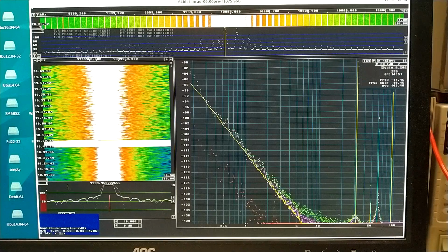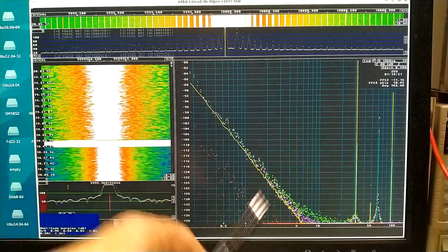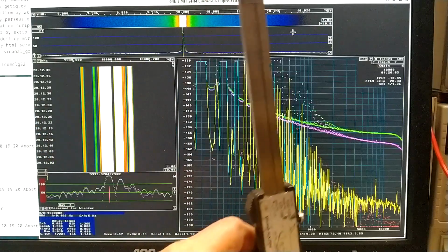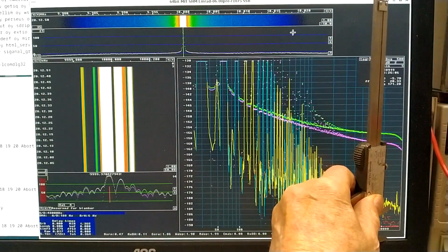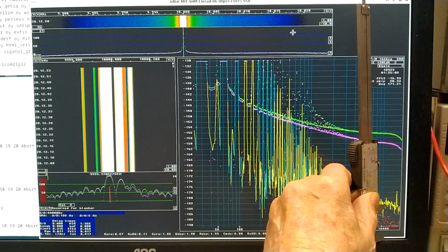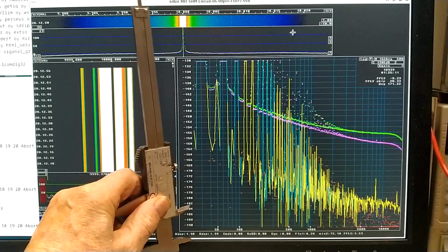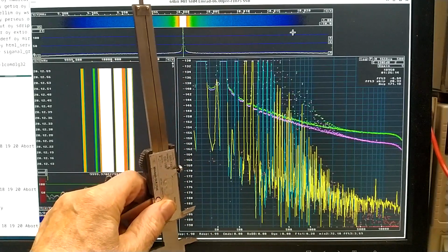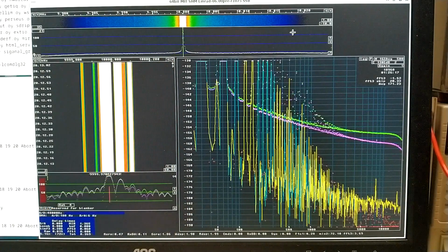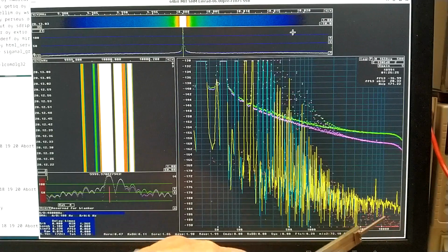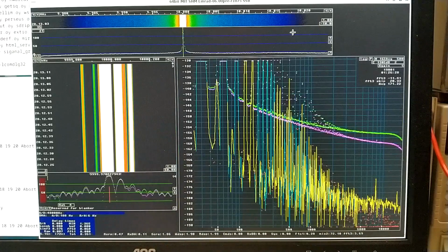After a little more than an hour, it is very clear that this here is much more noisy than what I see here. I will read a couple of values from the graphs. At 10 kHz, the noise floor seems to be about here. That's minus 182. So the improvement is a little less than 2 decibels. But on the other hand, the imaginary part is pretty close, so this can go down if I would wait long enough, which I'm not really interested in.